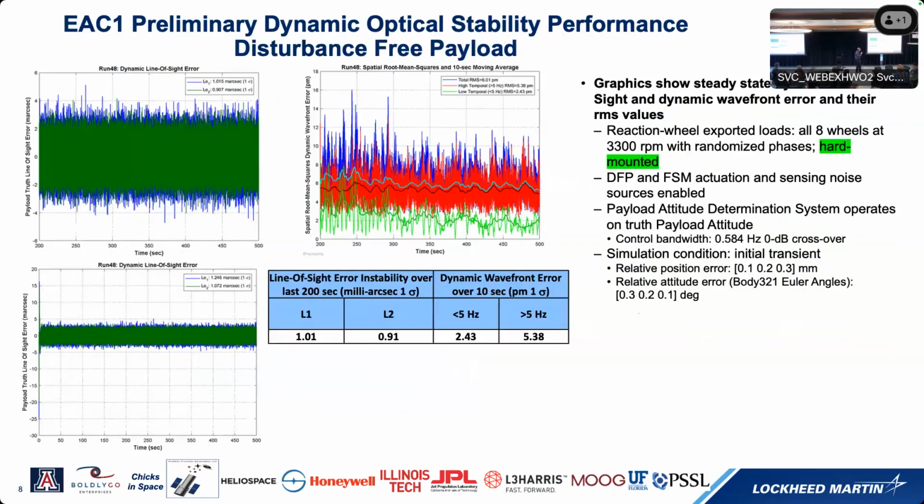Next chart, please. These are time simulation results. This is a simulation case where I introduced some error imposed between the spacecraft and the payload. What the system is going to do is try to bring the system back towards the middle of its operating range. That doesn't have to be done very accurately, but it goes on at relatively low bandwidth all the time. You can see that the transient is killed relatively quickly.